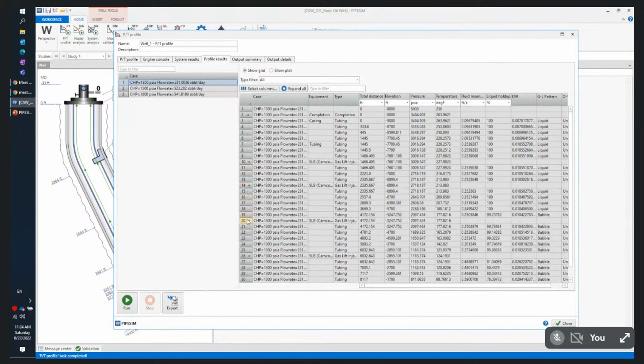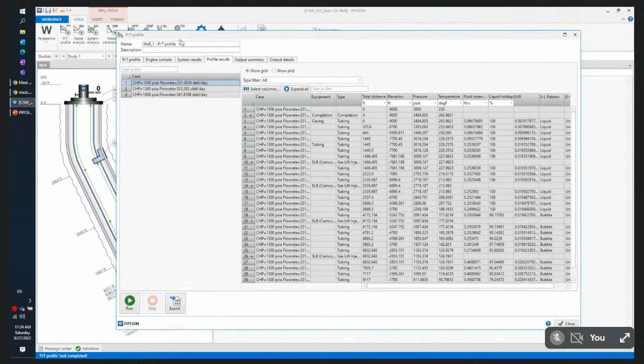So all the valves are closed. We are not injecting anything. You see? The gas lift injection is zero, and that's why we're going to the original rate, right? Because there is no gas injection. There is not enough casing head pressure to open the valves.